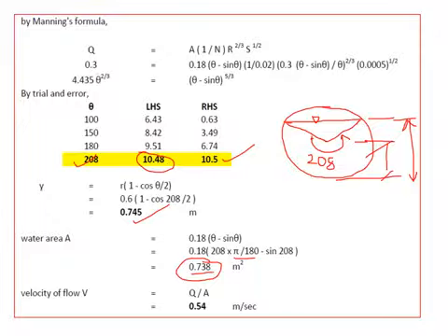In this case, it is either running 3/4 or half or 1/4, and therefore the top surface is a free surface which is subjected to the atmospheric pressure. That's the reason why it is classified under open channel flow, and we have solved some problems on open channel flow. Hope you have understood Chezy's equation and Manning's equation, where to use, when to use, and the various geometric elements. Practice three or four problems so that you get a hold on the equations that have to be used.